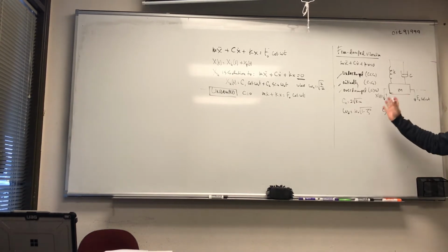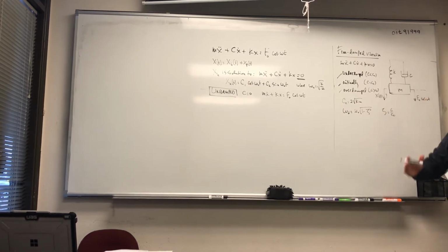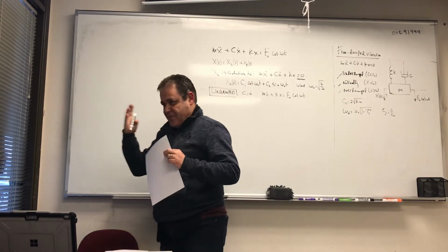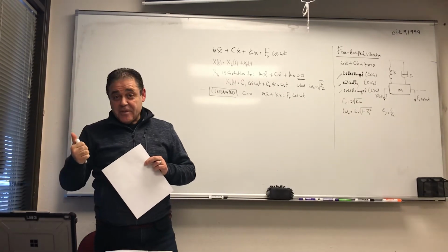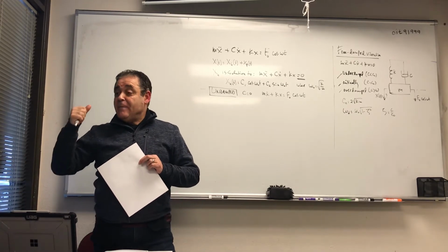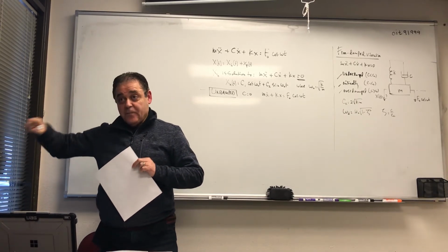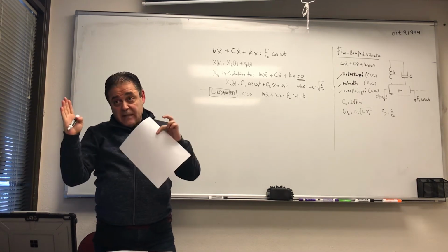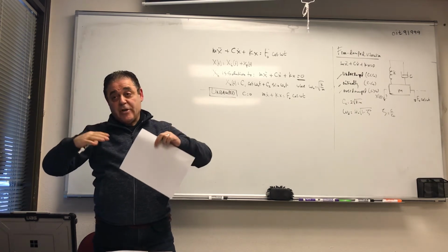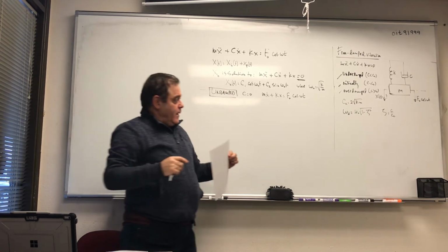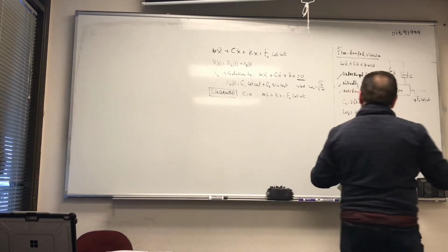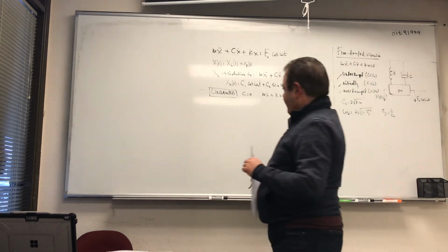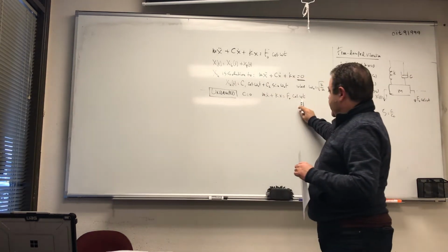That's kind of a nutshell review of essentially the class. There are 3 frequencies that you have to think about. There is omega n, which is a characteristic of the system. There is omega d, that's for free vibration, as it vibrates and comes to a stop, only for under damped, obviously. And when you talk about forced vibration, then it's just omega. So we took this little segue. Okay. So for the undamped case, C is equal to 0.